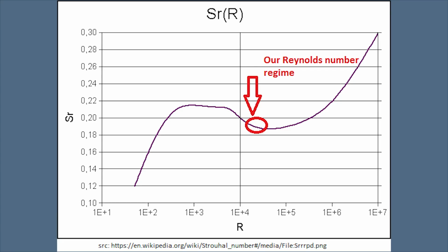The objective for this lab consisted of gathering pressure data within the laminar vortex regime at various Reynolds numbers. At the same time, flow visualizations were recorded to observe flow separation and vortex shedding. The pressure data is used to calculate coefficient of pressure around the cylinder and to calculate pressure drag across the surface of the cylinder. The flow visuals are used to observe the wake characteristics and the shedding frequency. In addition, runs are completed with and without a trip strip to allow comparisons between tripped and untripped pressure, drag, and vortex generation for different Reynolds numbers.